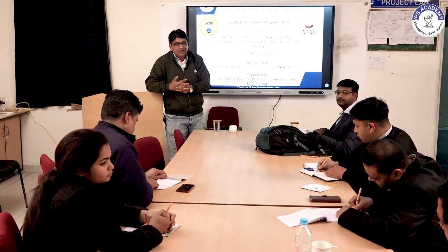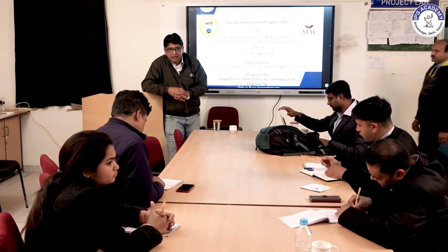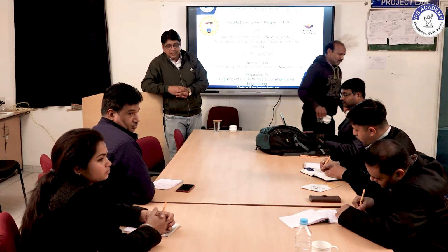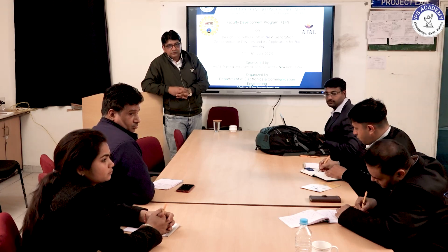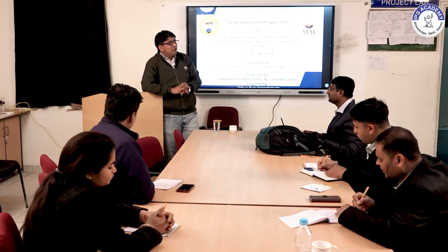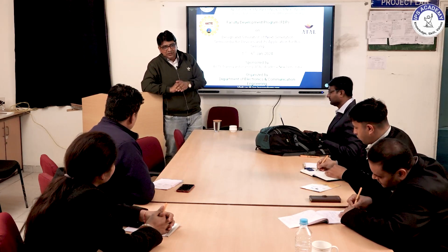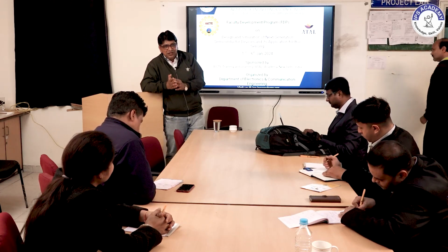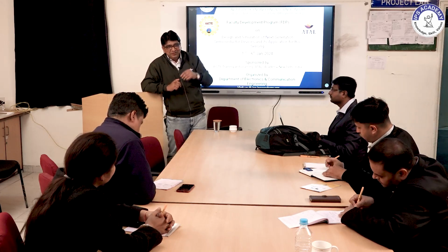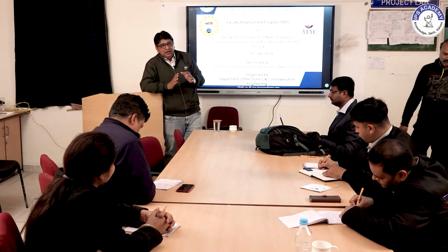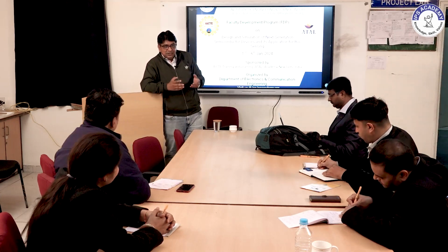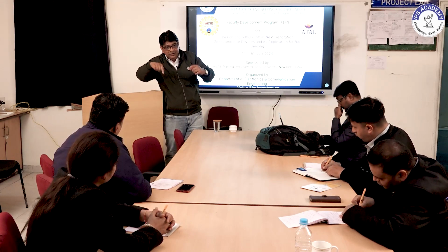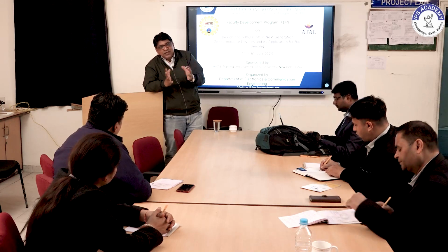Sir, any questions? Yeah. Actually, you discussed that there are so many issues related to short channel effects. But you showed one slide in which there is a long channel also. So why not discuss more on long channels? What is the drawback? Actually, I mention the long channel here only as the baseline, sir. How can we distinguish between the long channel and short channel? Micrometer, I can also say short channel with respect to millimeter. The reason is that that is the standard definition for the short channel, as researchers have quoted: if the channel length is comparable with the source and drain depletion barrier, then the device is called a short channel.